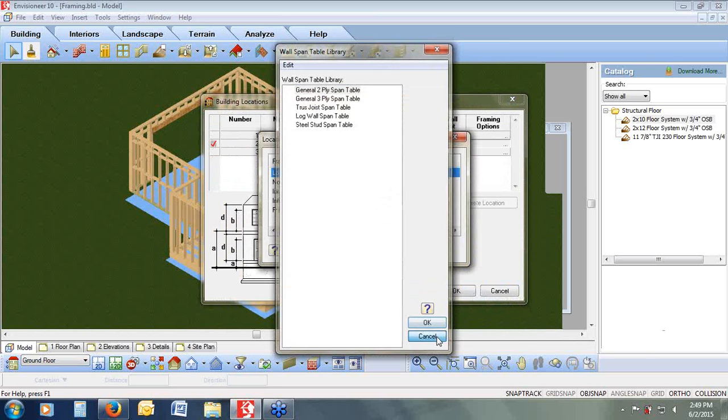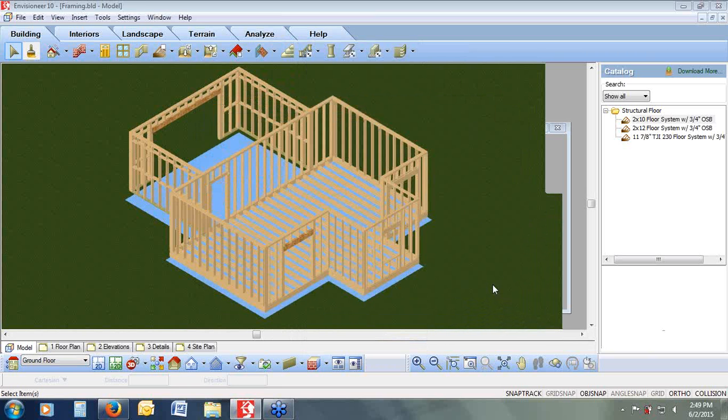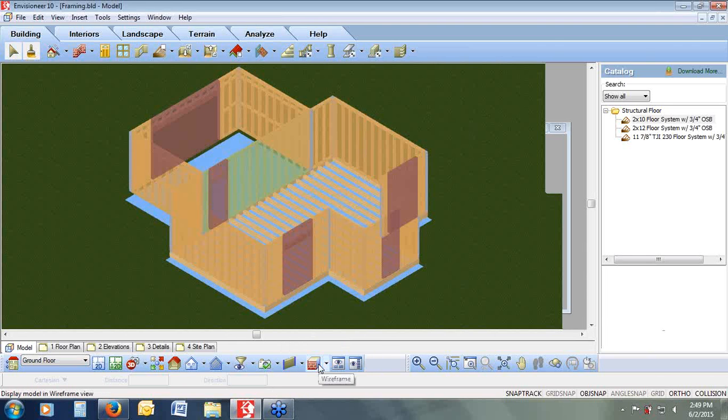And after you've chosen all of your defaults of how you want to frame them, if you need to change a particular wall or a particular opening on how it's being framed, that's when you can look at this framing mode on and off. With framing mode on, it will wash each of the walls. That allows you to select the framing and how the configuration is applied to that particular opening or wall. Again, the orange walls are load-bearing walls. The green walls are non-load-bearing walls. The rose-colored areas are openings.